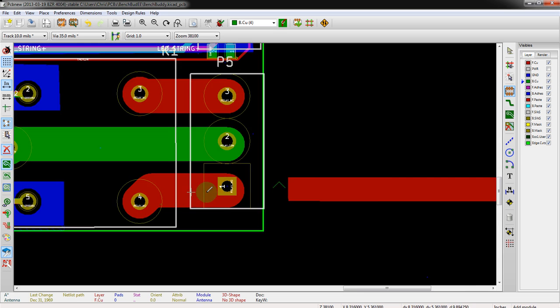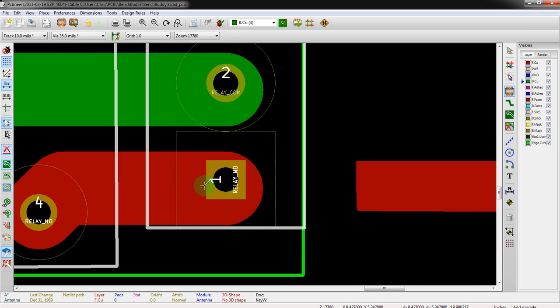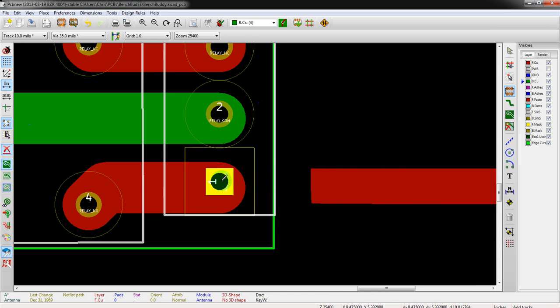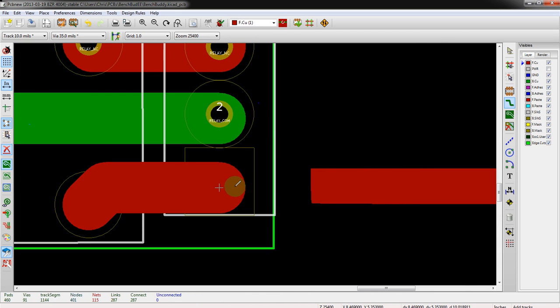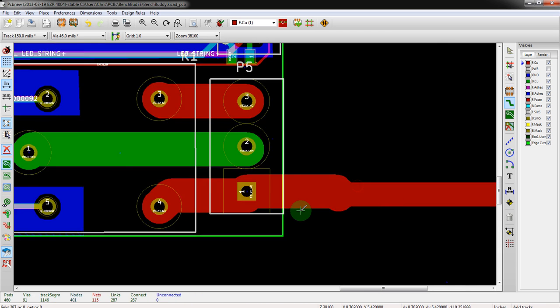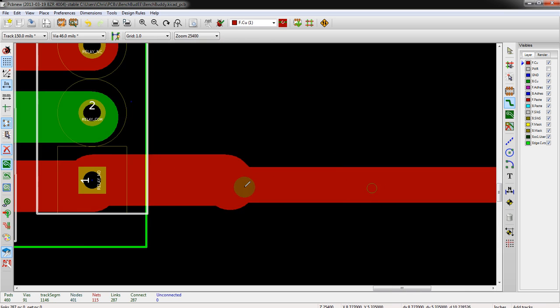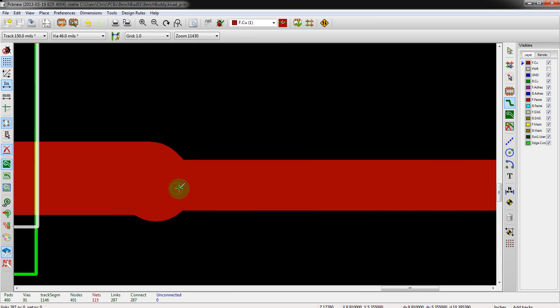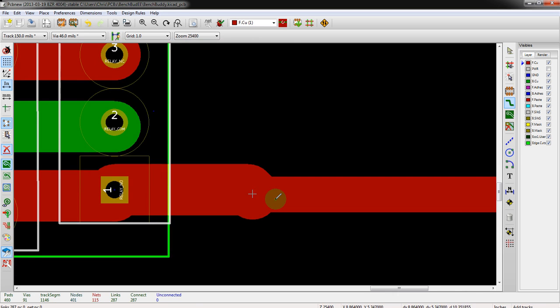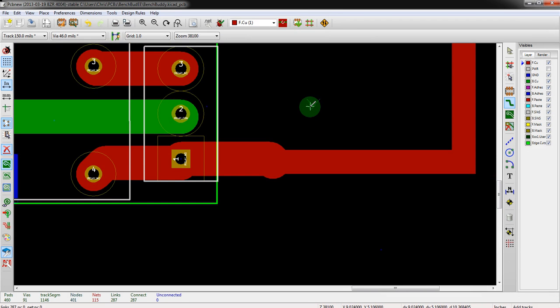If we wanted to connect this net, relay N0, then obviously it's not for an antenna, but if we wanted to drop that together, right? Oh, maybe that would work. I thought that we would need to put a pin in here. I'd like to show actually how to put a pin in here. I didn't think that was going to work actually, but I guess we won't know until we go to Gerbers. That probably would give us a huge DRC error, but let's try plotting.